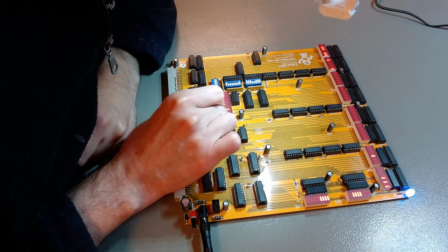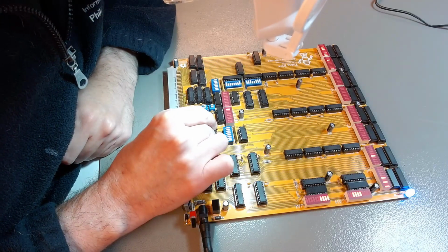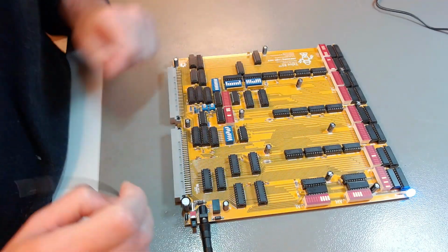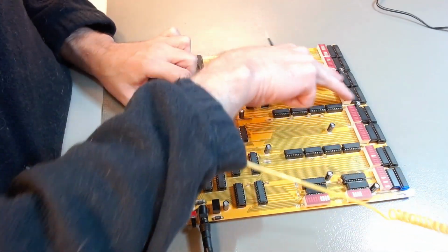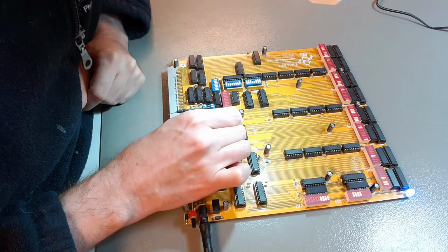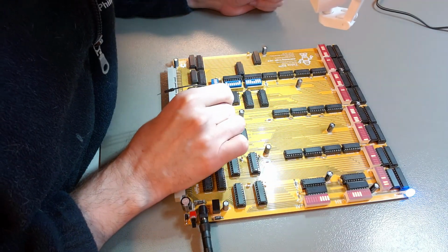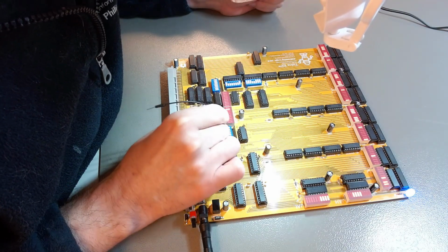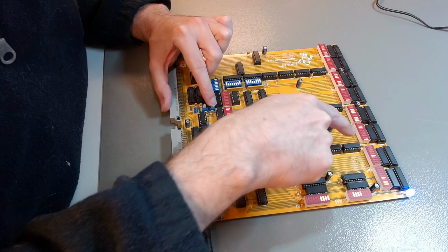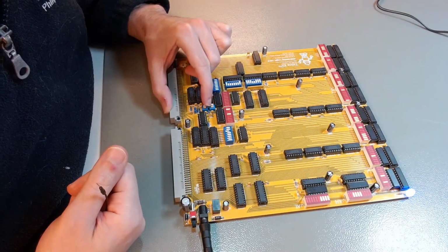So address register 1 load enable. Where is it? Address register 1 load enable. There it is. And address register 2 load enable. If I press clock now, these 2 values go here and here. There they are. So I'll now disable the load, and I will enable the count. First I will enable the count of AR1, and we count only on AR1. AR1 count enable. So if I press clock now, this will count and this one will stay where it is, and the PC will count as well. There we go. So that's working fine as well.